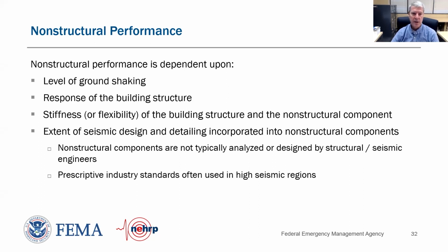So that's going to be a function of our seismic design and detailing for those. Generally, what you'll find is that non-structural components are not handled by the structural or seismic engineer. They're handled by the architect or the mechanical engineer or the electrical engineer for their particular discipline. And some of the stuff has prescriptive industry standards for high seismic regions. Ceilings are a good example of that.